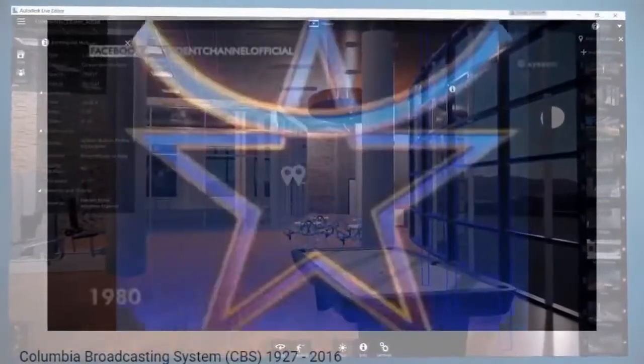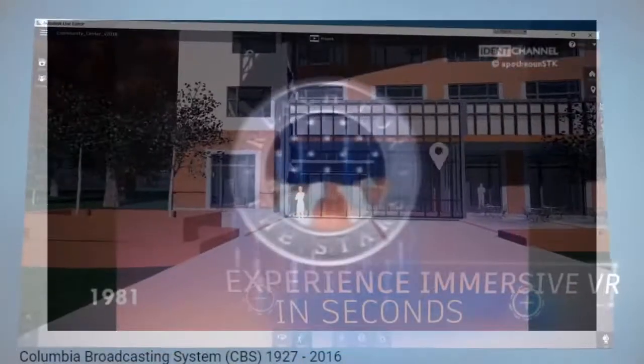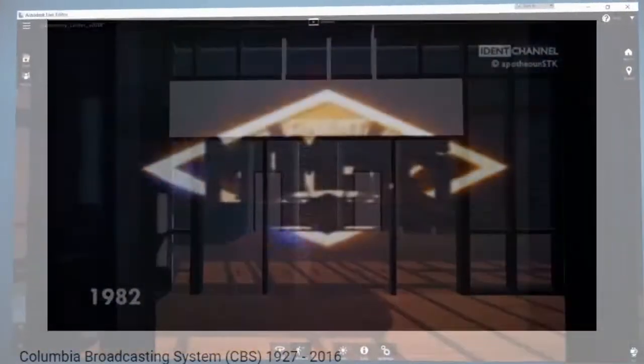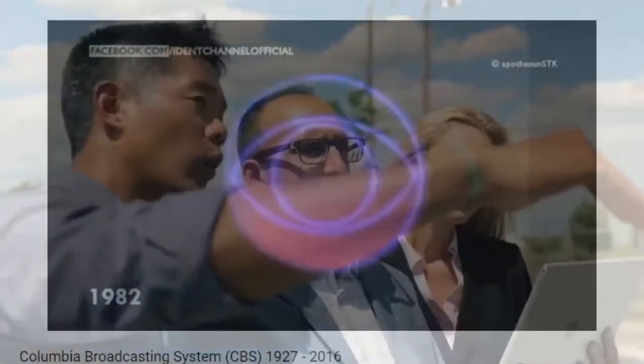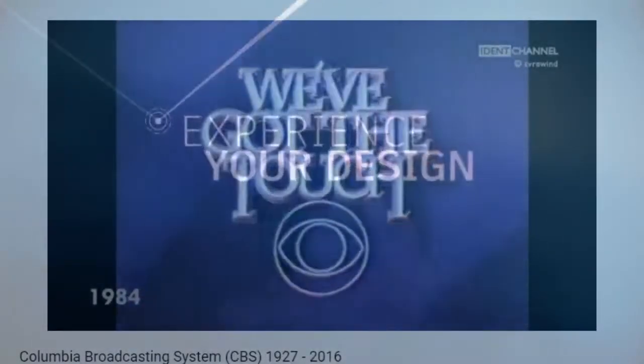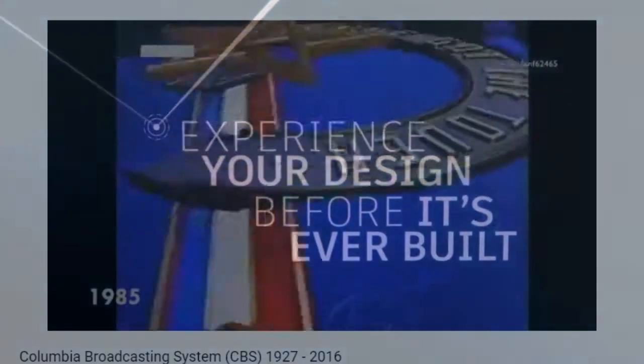If you look, it comes in under where the furniture and some of the other generic models are in place, landscaping. Just so happens to be built that way as a family. The family category is important because that's where it's going to place it within the family hierarchy. And if it's the wrong category trying to go in from a discipline that you're inserting, you get an error message, wrong family. So it's a pain, but you have to create your families, and when you get to that in the next chapter, you have to create your families with these parameters, or they'll be a bit off kilter.